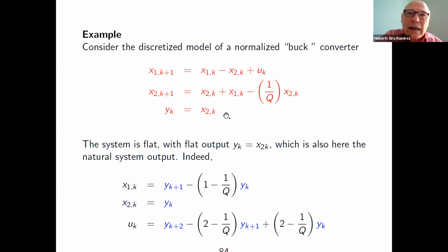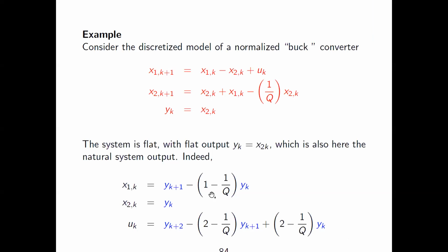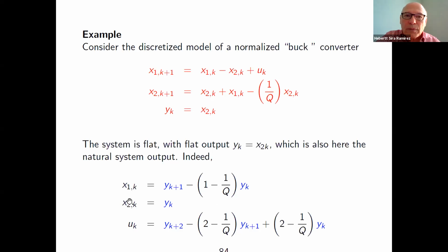In this particular case, in which the flat output is the only output of the system, the parameterization of the input gives you the input-output parameterization. And the state parameterization is what is probably new for many people: that the properties of the state evolution, and the concepts attached to the state, can be recast in terms of this special output y.